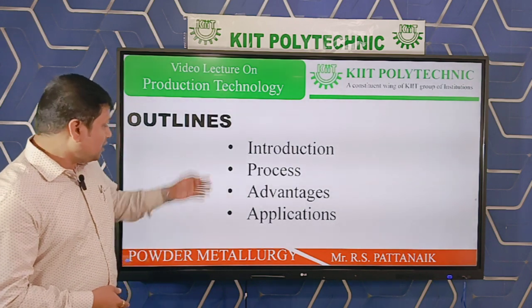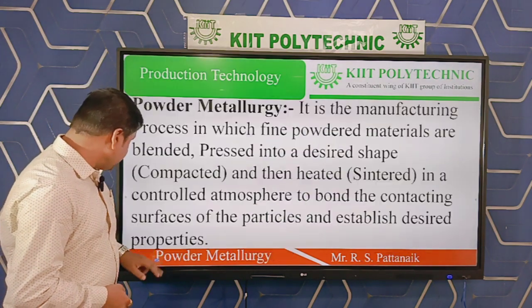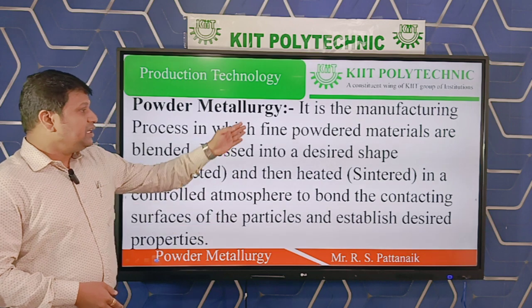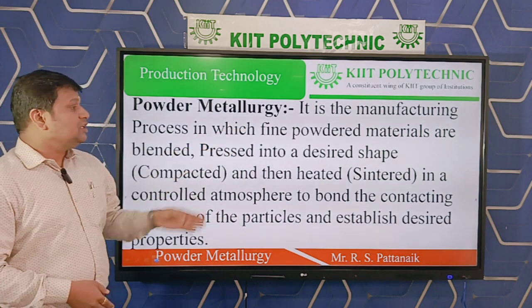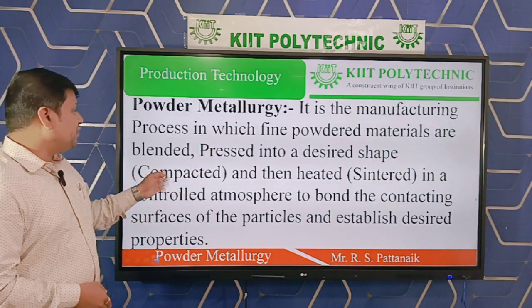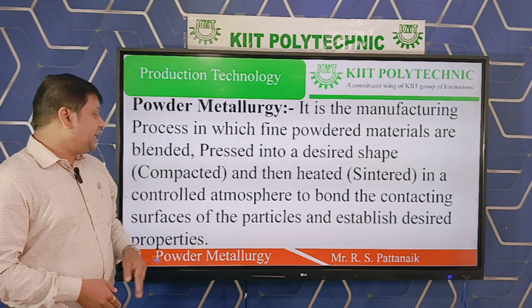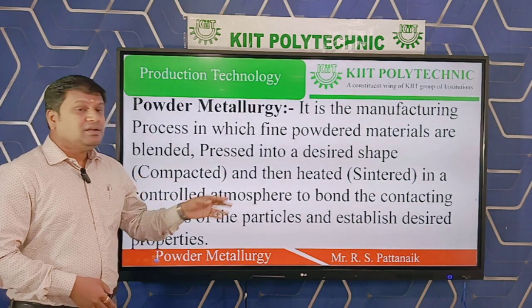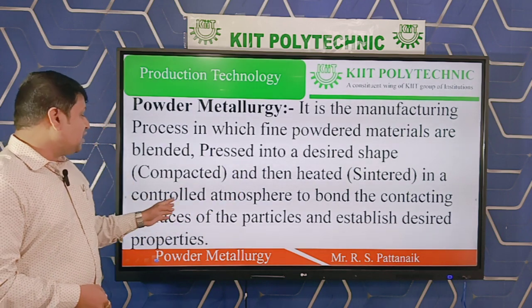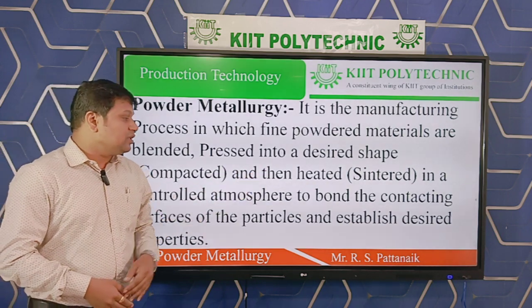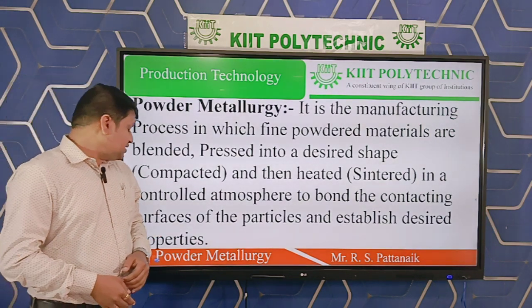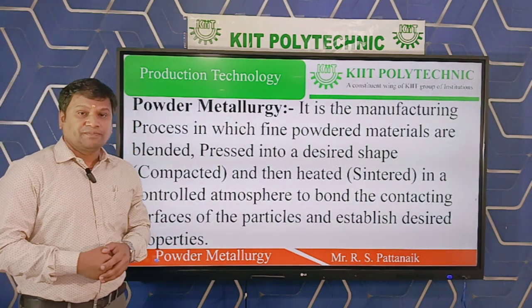It is the manufacturing process in which fine powdered materials are blended, pressed into a desired shape, which is known as compacting, and then heated, which is known as sintering, in a controlled atmosphere to bond the contacting surfaces of the particles and establish desired properties.